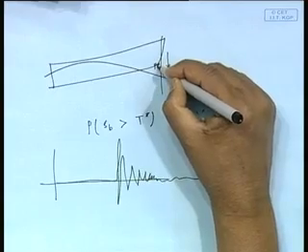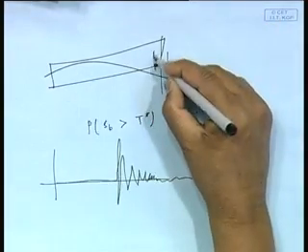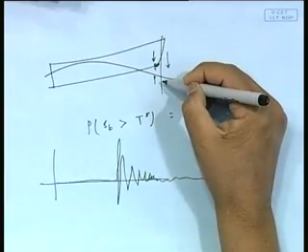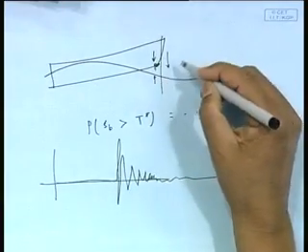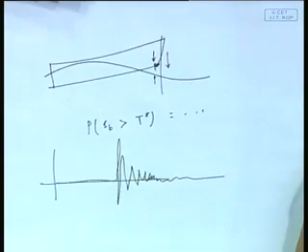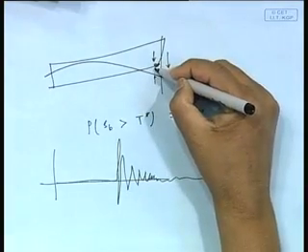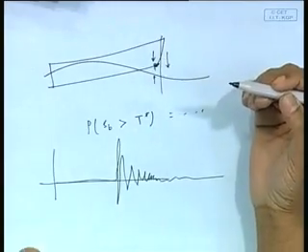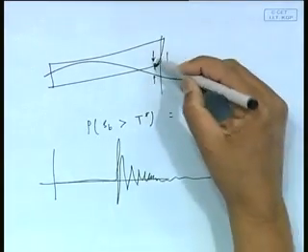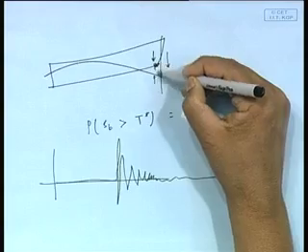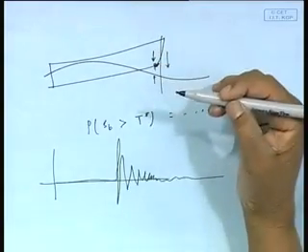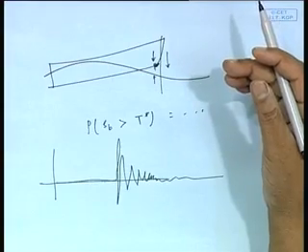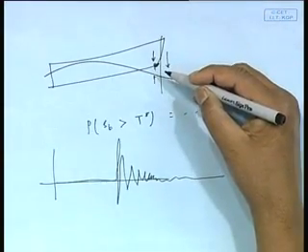So this bottom will be undergoing a large pressure because it is entering here, and it depends on the impact load. Now this impact load will obviously cause a very large vibration on the hull, basically like a hammer banging it here. Now when will it happen? Nobody knows exactly, but what we do know is that for it to happen, this bottom might have to come out and re-enter, and it has been found that it must re-enter beyond a certain threshold velocity.